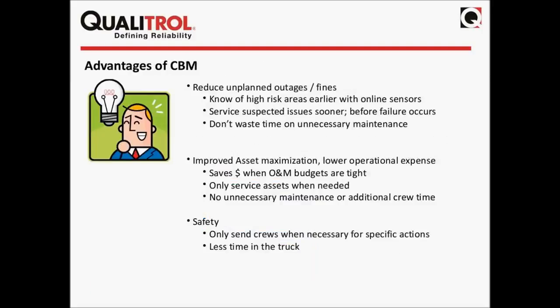So what are the advantages of doing something like that? And this is exactly how the breather fits into this scheme, because it's smart. You couldn't do this with a traditional breather. You would have to do time-based maintenance. You would have to send somebody out there. But with our smart breather, it fits into this condition-based monitoring because you can reduce unplanned outages and fines.